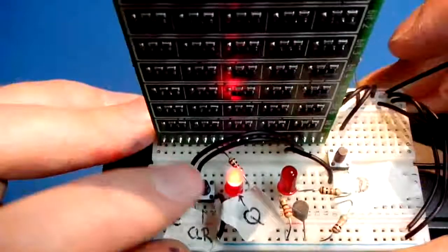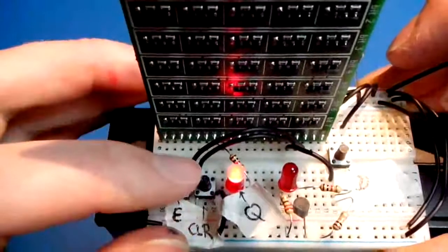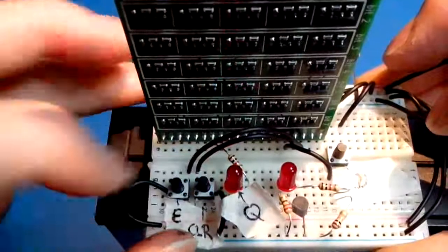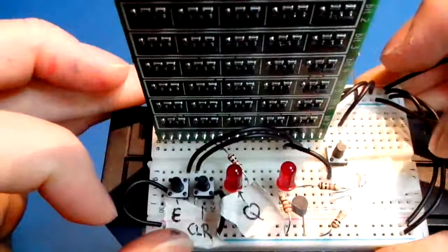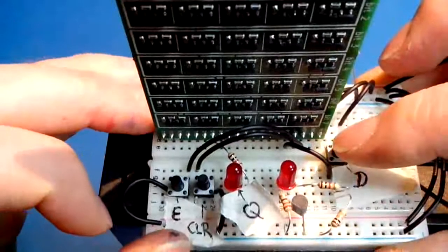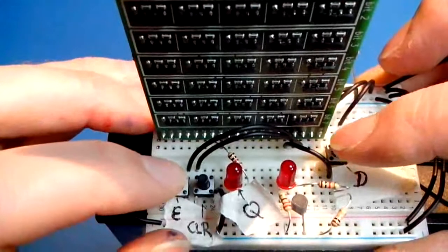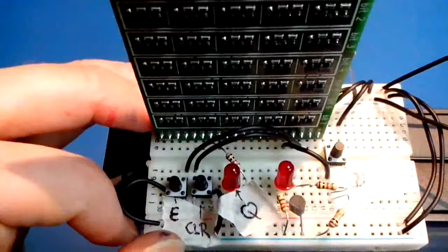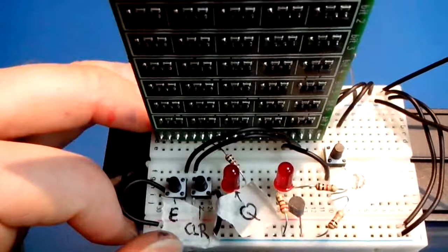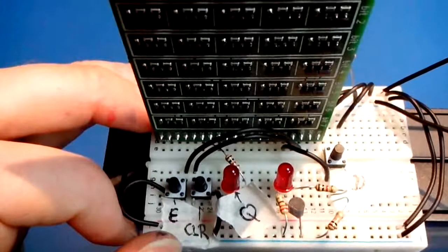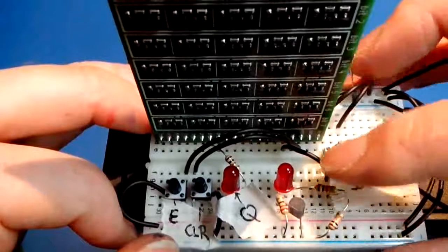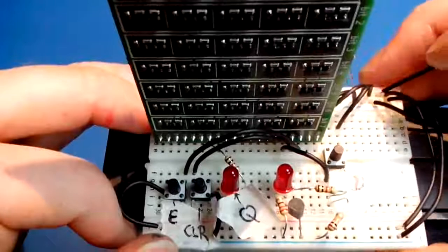No matter what the output is, if you apply a high signal at the clear input, as the second button, pressing that now, the output Q is reset to 0 or low, right? And in the context of the CPU, the reset signal is system-wide, so you apply a reset signal externally and the whole system would reset to the initial state, and that's good in this case, all outputs are 0. So that's how it works basically.